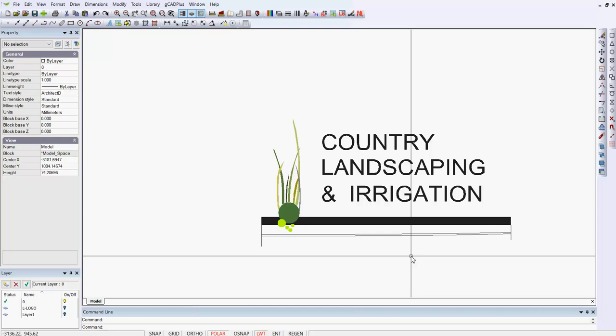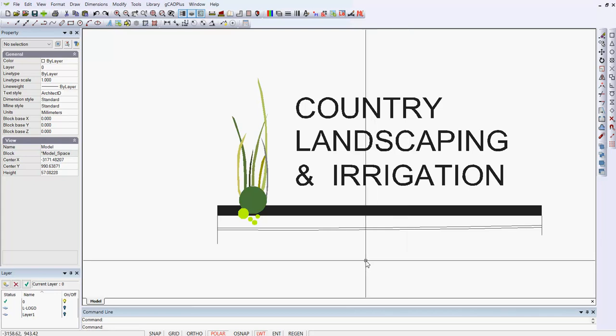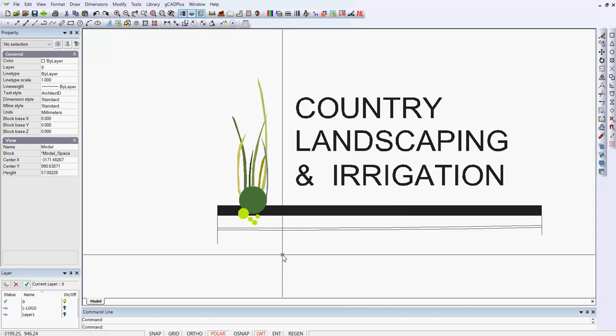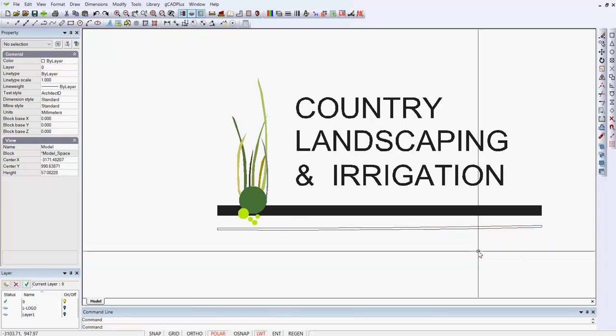In fact, if you pick in the wrong order, the arcs disappear, and you end up trimming off the wrong part of the arc. I'll try and demonstrate that in a moment, but let's see if we can do it properly first. So repeat trim. Again, we want to know which is the cutting edge. Now this time we have to pick this arc and this arc, the 2 new arc pieces that are left. Right click, then knock off bits like so, and we're done.